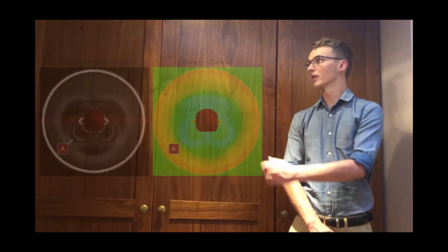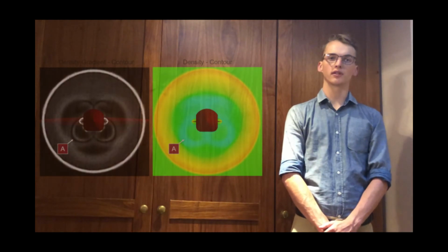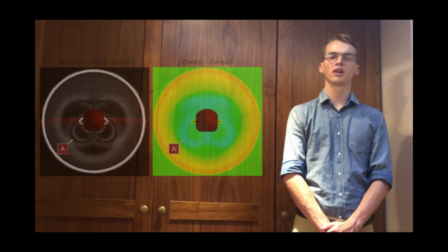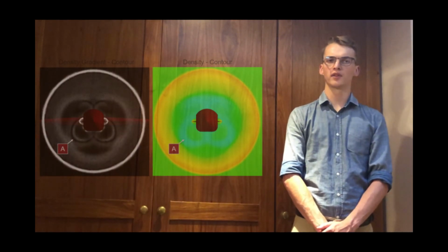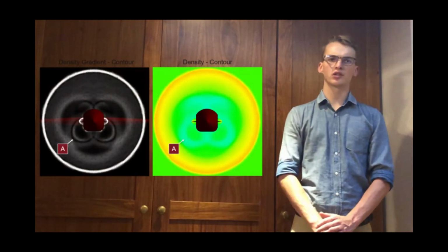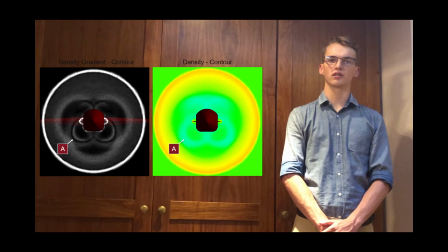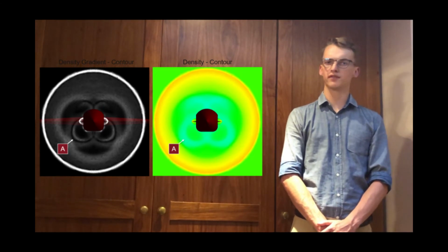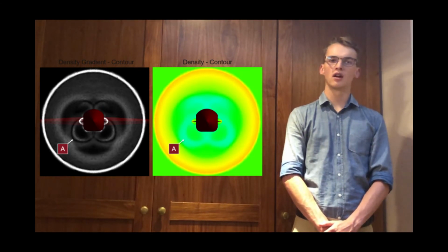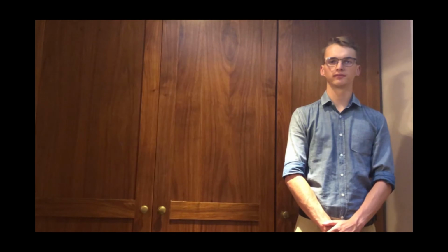Cross-sections were taken through the flow at several points along the body, a valuable tool in interpreting the flow field, with several complex, interesting flow features appearing. For instance, this image shows the cross-section taken just aft of the leading edge fuselage intersection. The low-density, butterfly-like pattern marked as A arises from the overlapping curved expansion fans originating from the corners of the fuselage.